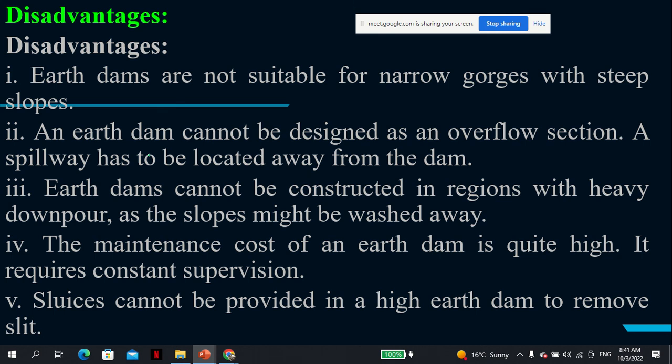So with time, and I'm not saying this is exactly what happened in Solai Dam, but the issue with Solai Dam, I think 3, 4, 5 years ago, water was seeping through, I think, 30 meters of impoundment, and water seeping slowly. And I'm even wondering how responsible were they? Is it the county government? Because when you see something like this, you really need to take action, because the other option is catastrophic failure. So when you see water seeping, that's not a good sign. Action should have been taken.